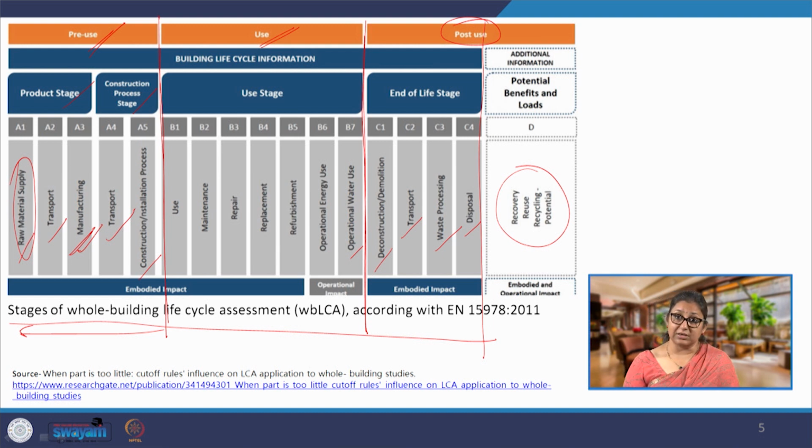For multi-storied buildings, we can't be using very heavy materials, we cannot be making very thick walls, while if we have buildings which are horizontally spread and only on ground floor, where land is not as difficult to obtain, where we have availability of land, there heavier materials can be used which have lower GHG. But the moment we are looking at vertical buildings, there the lighter materials, most likely synthetic materials or metals, will always have higher embodied energy.